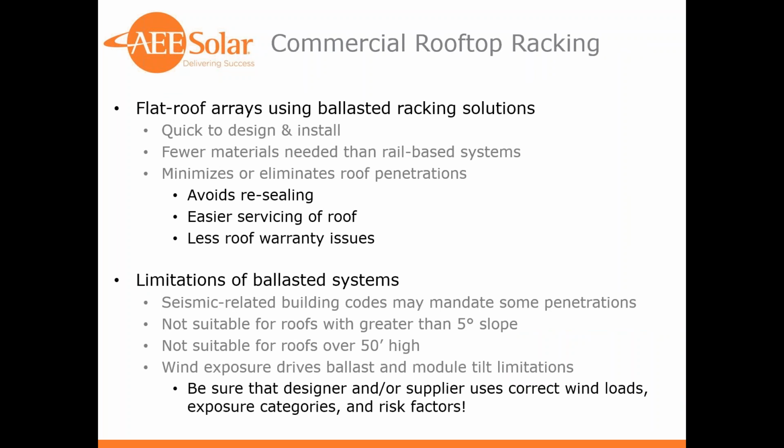Okay, commercial rooftop racking. So flat roofs are ideal for use in ballasted racking systems. Ballasted systems are quick to design, easy to install. We have the tool for one of those systems that we can, usually if we have all the inputs, configure a system quite quickly and get you something fairly easily and quickly to your customer for feedback.